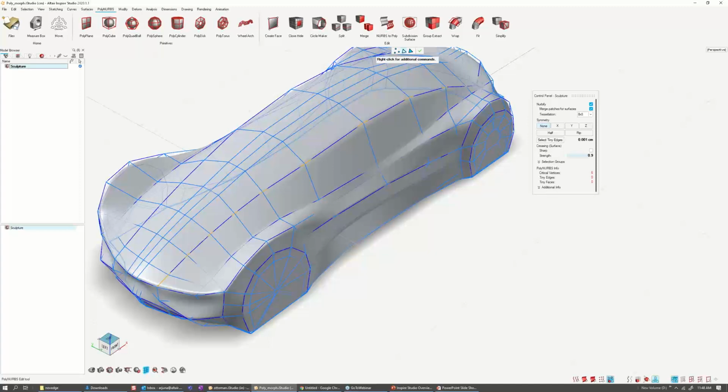I have some options for interpolated curves. I have an auto CV for 7 and for 9. These give me some ways of changing it. Let me go to, I think this is the 5 CVs. So I can go to my front view. When I pull on one of these, you can see that the shape of the curve will change and also the vertices will move. But I didn't have any symmetry on, so on this side nothing happened. I could have turned on symmetry and the same thing would have happened to that side. But that is one part of it.